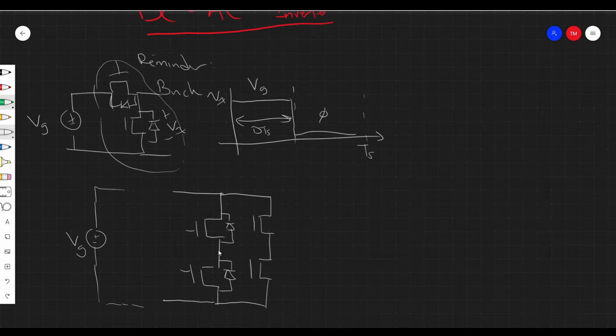And you might be thinking, well, that has to be a positive voltage. How do we produce an AC voltage, right? How do we produce the negative voltage? And the trick really comes by looking at the difference between these two voltages, right? So we have the voltage from this leg and the voltage from the other leg, and the voltage we look at is the difference between them. So we want to look at plus minus, I'll call this Vx, right? This is the voltage we want to consider. And what does this Vx look like? I'll call it Vx prime. What does this Vx look like?